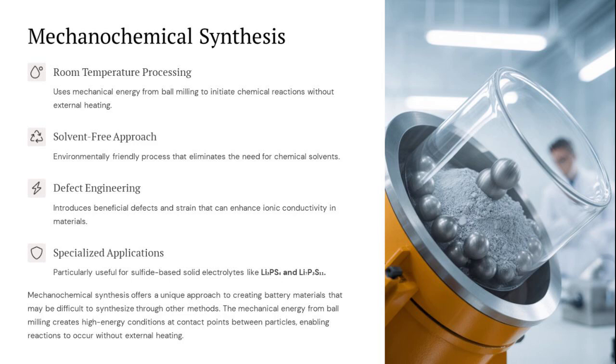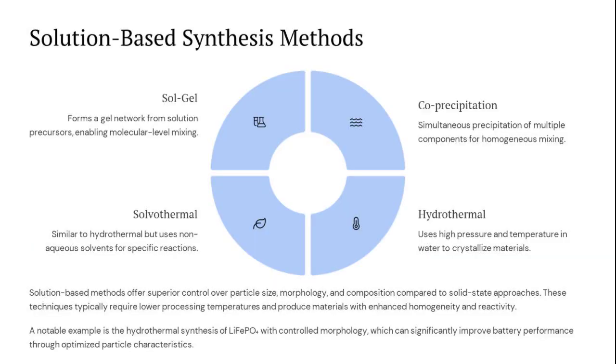However, challenges include potential contamination from milling media, difficulty in scaling up, and limited control over the exact defect structure introduced. Solution-based methods. Solution-based synthesis approaches include sol-gel, co-precipitation, and hydrothermal/solvothermal methods. These techniques generally offer better control over particle size, morphology, and homogeneity compared to solid-state methods.